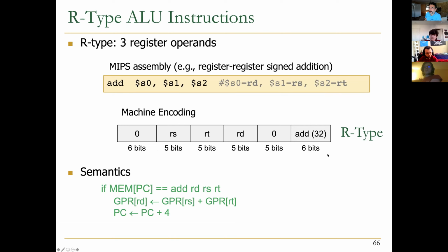You know exactly what bit number 0 to bit number 31 are, how you need to locate and retrieve each bit and piece. And here, how many pieces do you have? 1, 2, 3, 4, 5, 6. This 6-bit field and these 5 bits, you are not going to use them, at least in add, in R type. But the other parts, these 6 bits, these 5 bits, these 5 bits, these 5 bits, are going to be used at the microarchitecture in order to implement this semantic, okay?